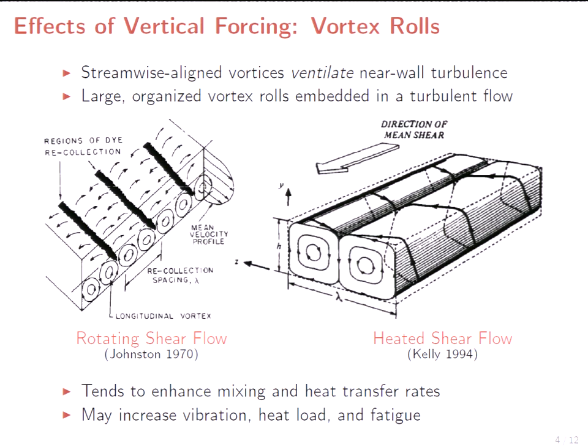In the context of, say, rotating shear flow, in a gas turbine these turbine blades are rotating, and they're often rotating in such a way that on one of the sides of the airfoil you'll be able to generate these longitudinal streamwise vortices. If, say, on a turbine blade the incoming gas is very, very hot, you want to be able to keep the turbine blades cool so they don't melt.